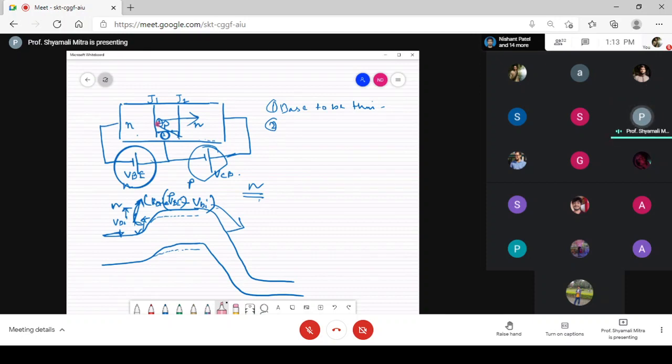Okay, now the majority carriers, which are nothing but electrons, the probability of finding an electron in this region is more compared to this region, because the number of minority carriers, which are electrons in this case, will decrease through time and distance, as you will find more and more recombination centers over here, that is the holes. So the minority carrier distribution, that is the minority charge carriers, will decrease from this position, from this height,